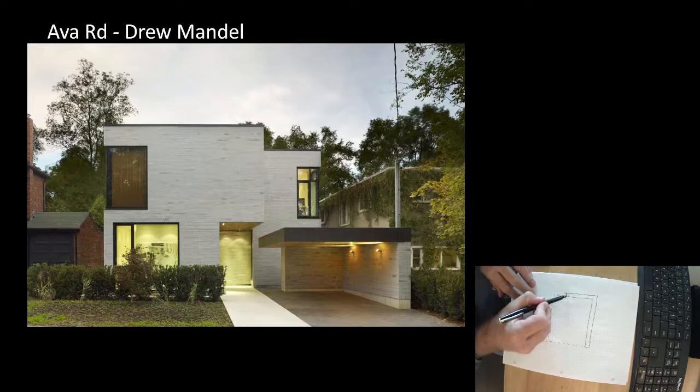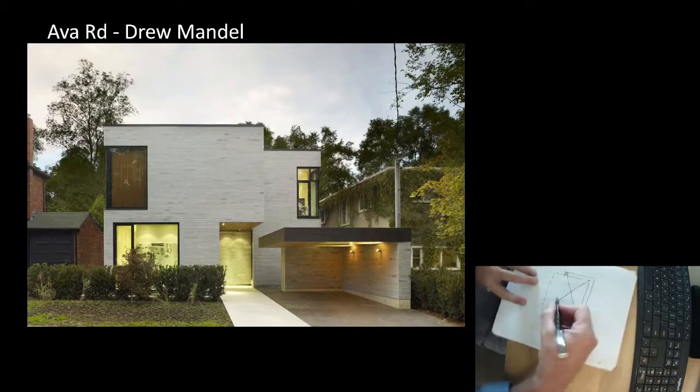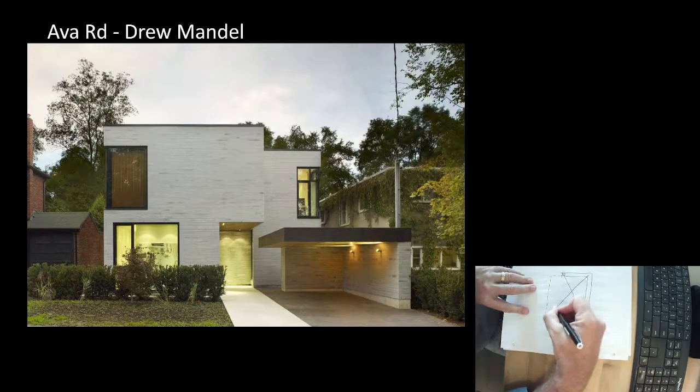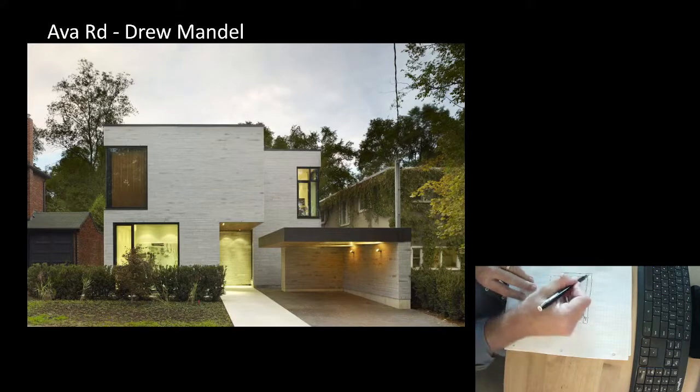What Shannon did is took a beam across like this. I'm going from memory because it's been quite some time. She took a simply supported beam across like this, so it sits on the concrete here and here, piece of cake. And then another beam that comes like this and cantilevers out. Now this can be stacked one on top of the other as a totally valid load path.